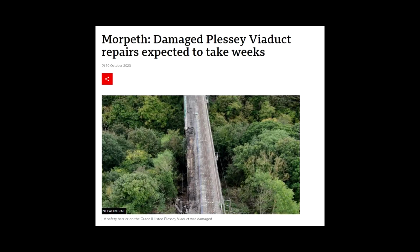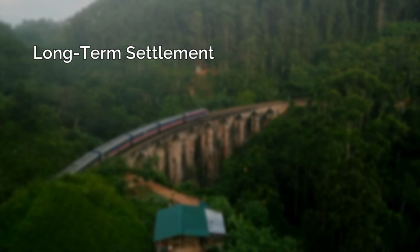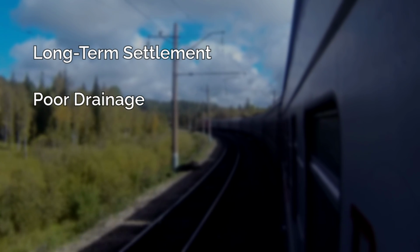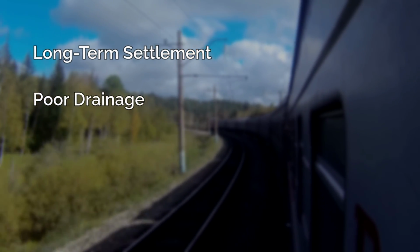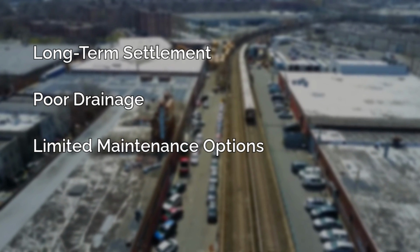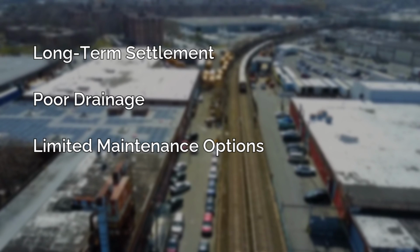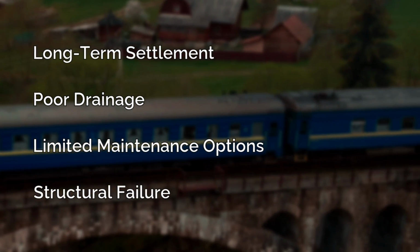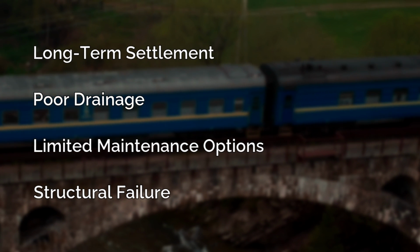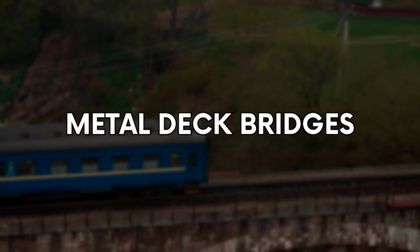So, the track problems. Long-term settlement, often caused by deterioration of the fill material or slow subsidence of the support structure itself. Poor drainage. The fill we spoke about traps water, which can lead to wet beds and the pumping of the track. There's a limited amount of lift that can be applied, and the risk of overloading the structure is very real. Structural failure. These bridges deteriorate and fail. Bulging or cracking may be subtle, which makes them easy to miss during inspection and harder to manage over time.